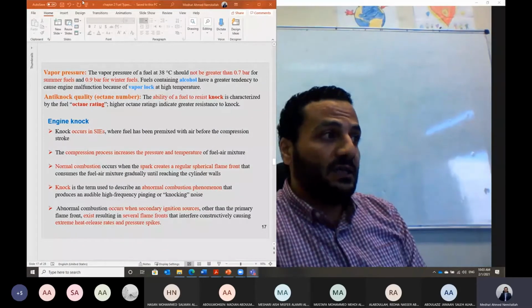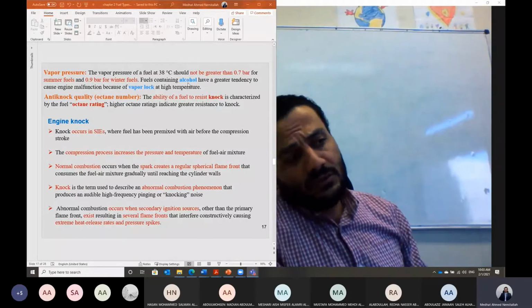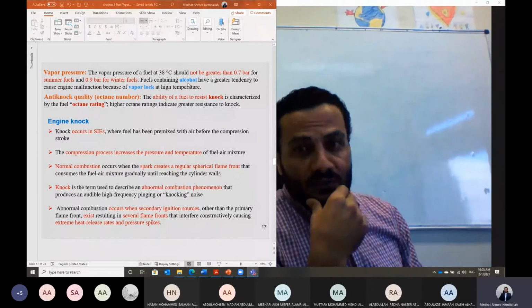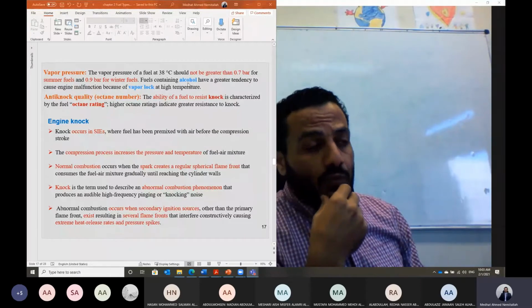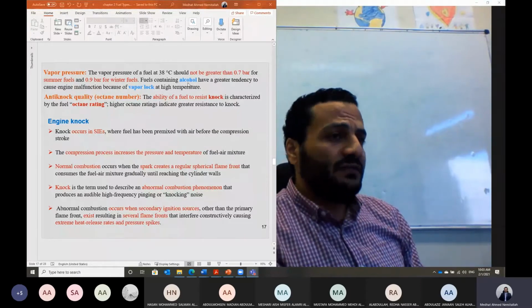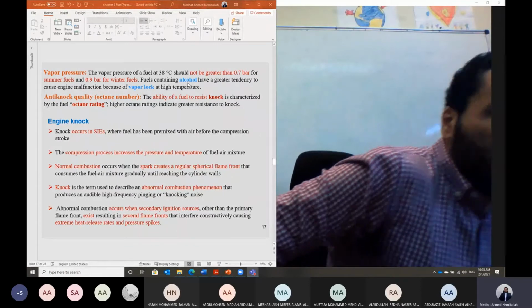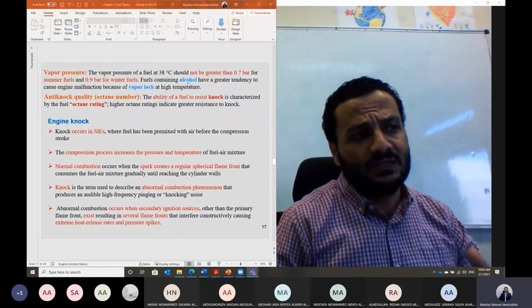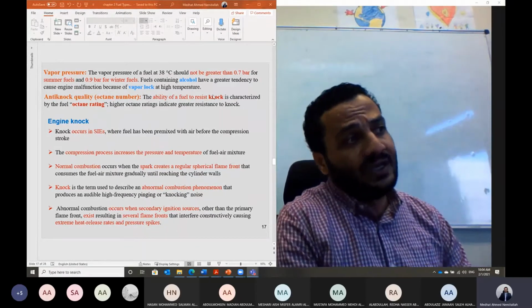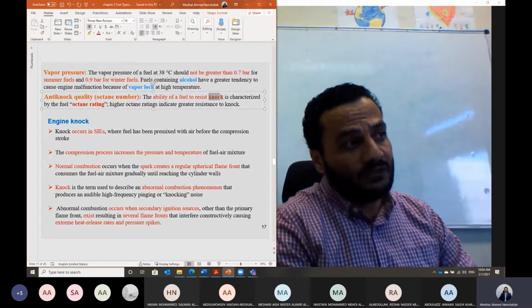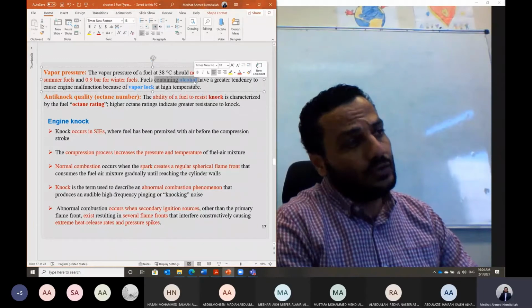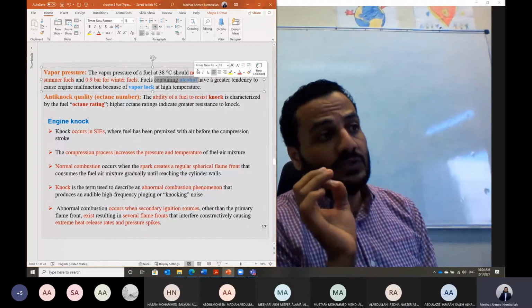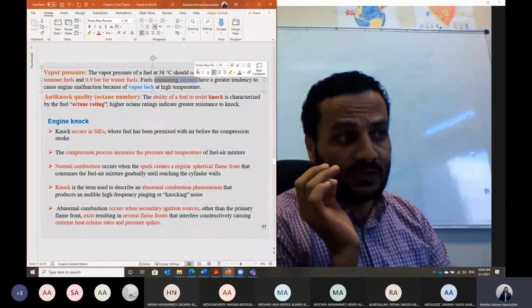We said last time also that there are some fuel additives, mainly alcohol. Usually we add some alcohol to the fuel in order to improve the fuel quality and the resistance to self-ignition, and the resistance to what is called fuel knock. So in some cases we add alcohol, but this addition should be very limited, because alcohol is a very volatile substance.